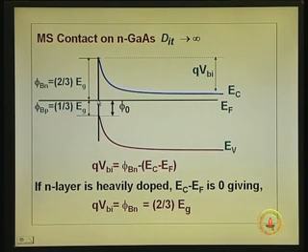We will come back to the details of the physics of this a little bit at the end of the lecture today. But right now, what we say is the Fermi level will align itself with respect to E naught. As a result, this is phi naught, and this is Eg minus phi naught, that is 2/3 of Eg.